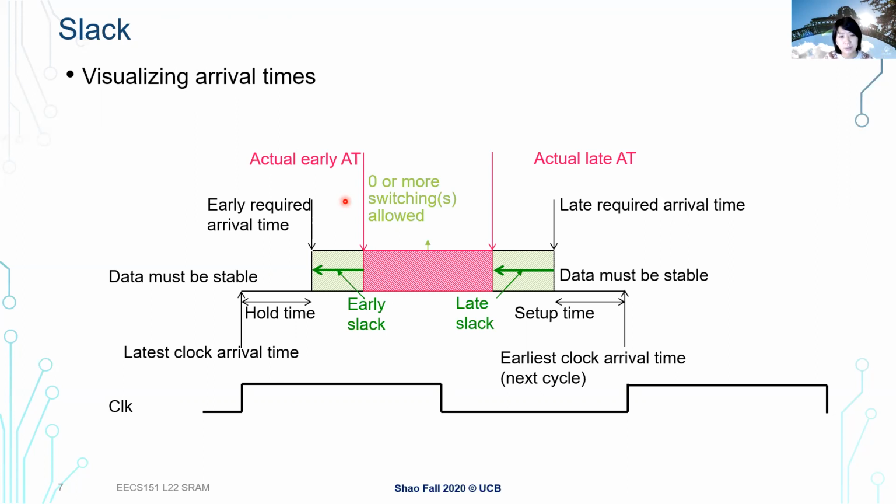It doesn't take the entire clock period. And typically you also notice it will report the slack that exists in your design, right? So if you have slack, you basically have some buffer to handle other conditions. We'll see later some of the non-ideality will also eat some of the slack time that you have. But if you also want to optimize your design, you can add more logic into your design to have smaller slacks, to make sure you maybe have a smaller number of stages, to make sure you use all the available time that you have here.